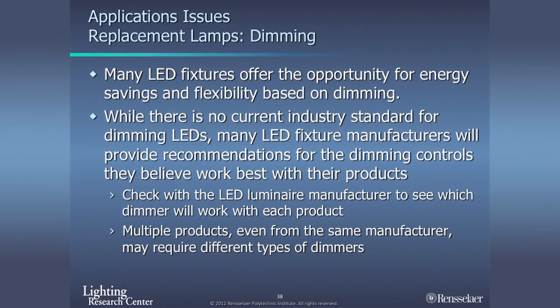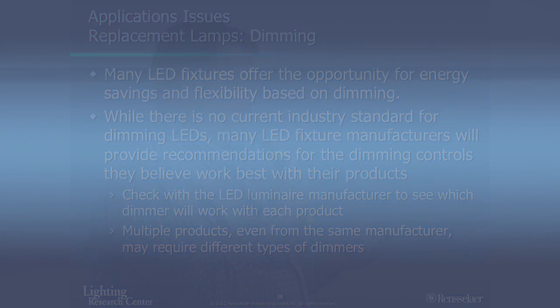The bigger problem is, when you're doing a job, you typically have 3 or 4 or 5 types of light fixtures in it. If they all have dimmers, and all the dimmers are different, that's a headache for installation. Think about that installer. Do you think he's really reading the spec sheets and saying, this dimmer goes with this light fixture? No. He's, oh, this is a dimmer. And he puts it in the wall, and he doesn't know what light fixture it's dimming. So you have to be careful. We've seen some jobs where there were 5 different control technologies for each of the different types of light fixtures. So it becomes a little more complicated, one more thing you have to pay attention to, either in retrofit or in new construction. It's worthwhile, though, because if you do follow the instructions, typically it will work.